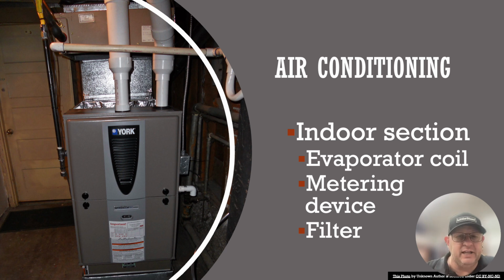We can glue these traps together, but there is a trap out there that's in a clear coated plastic that enables us to look inside of it and see whether we need to clean it or not. During the normal service of an air conditioner, this is one of the things that you should do: clean out the trap on the evaporator drain so that we are making sure it's clear and doesn't drip any water on top of the furnace or air handler or into the environment that the unit is sitting in.